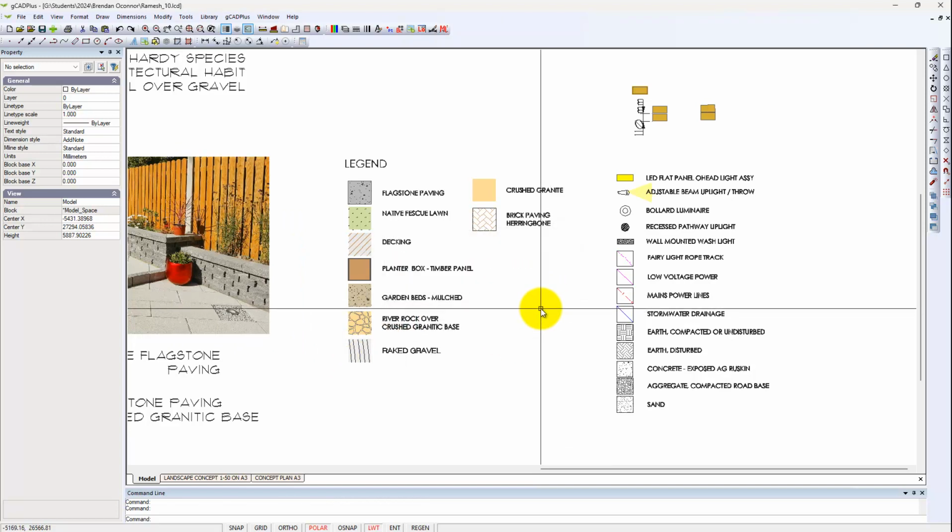So we now know, let's imagine this came in from an architect, although clearly it didn't, but it's really good to be able to check your drawing. If you're passing a drawing to a designer, you could do that check, write out save as a DXF file and send it to your architect, and they will be able to load it. So this tool's an interesting one, but the take-home lesson is try and avoid having spaces within block names or at the end of block names, and probably the same with text files, and the same with layer names.